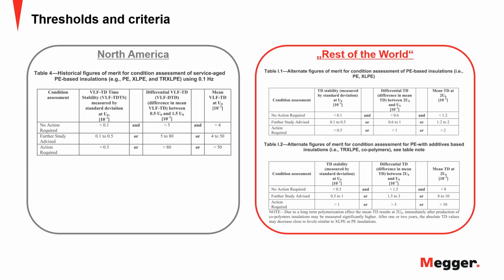Another very interesting thing is the company, which I took as an example. They also have the work practice to cut out all three phases, no matter what, when they have a fault. So let's say A phase fails, they will cut B phase and C phase as well to keep the cables the same. Then they check, maybe is there a common denominator, who built the joints and whatnot. So they do all this additional assessment far beyond just the numbers. The numbers are just a starting point.